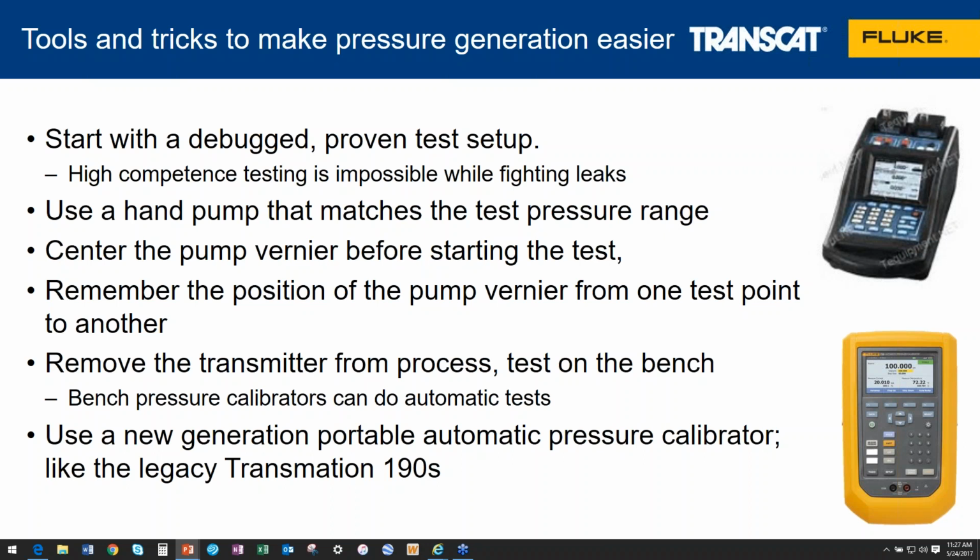And before you perform the test, center the pump vernier before starting the test. Invariably, if you don't center the pump before starting the test, Murphy's Law says that if you need to turn it one direction and it's on the stop, that's going to be the direction you're going to want to turn it. And remember the position of the pump vernier from one test point to another. There's a little bit of tribal knowledge in working with test pumps that if you remember where it's left in its vernier phase, you can overcome its position by virtue of the way that you pump to your target pressure with the pump.